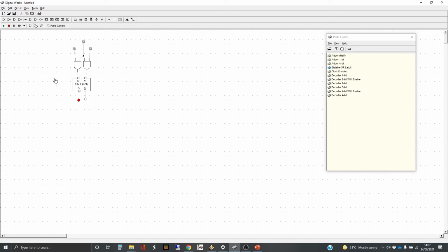When we turn the circuit on and make it run, it's immediately set itself to Q. Let's remind ourselves, reset is the one that will change it. If we put the reset line high, nothing's happened yet until we put something in the clock, which is the enable. And that's when it happens. If we do it again, obviously, because it's on the reset, it's already set, nothing's going to change. We change that back to S, and then we hit the enable. That actually happens. So it's not a big change, but it is quite important when we're putting together a larger set of components and we want things to synchronize and happen at various points in time because we've got sequential programming going on.